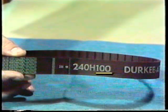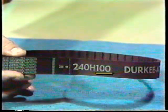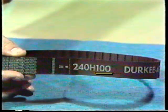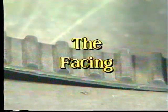The third part of the code indicates the width of the belt, again in inches. In this case, 1.00 means 1 inch. The last part of the belt is the facing, which covers the teeth. Normally, the facing is nylon. Under normal service, it polishes to a slick, shiny appearance. Although this facing is the only part which is subject to much friction, it will normally outlast the other components of the belt.